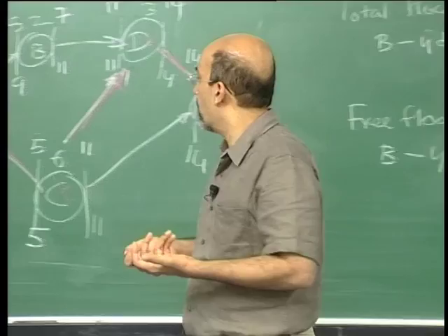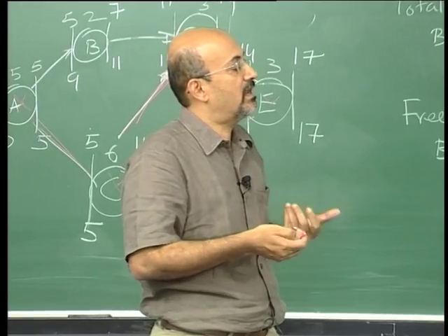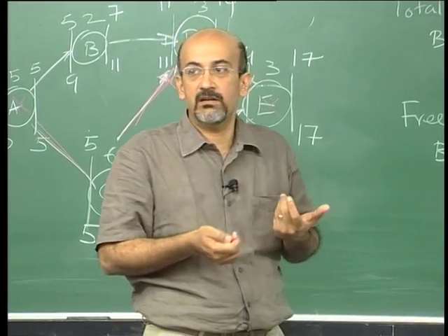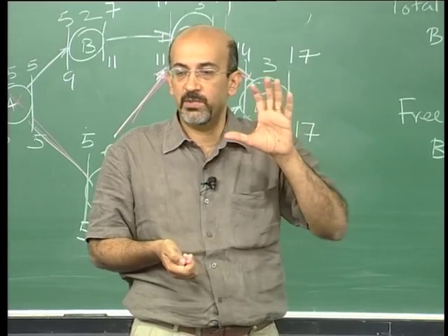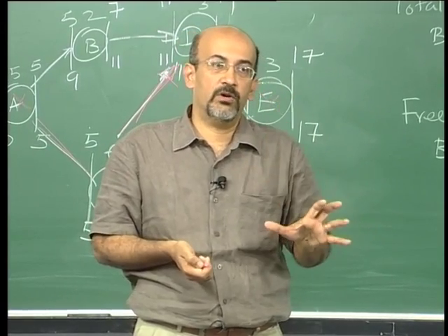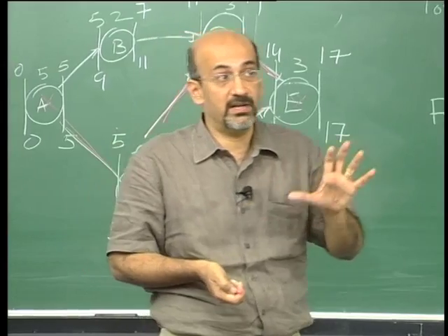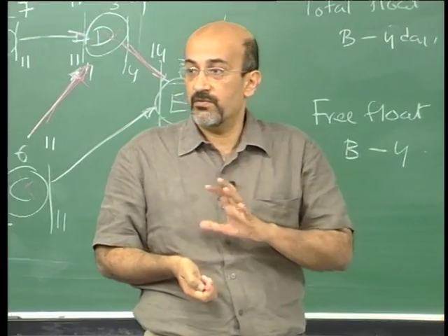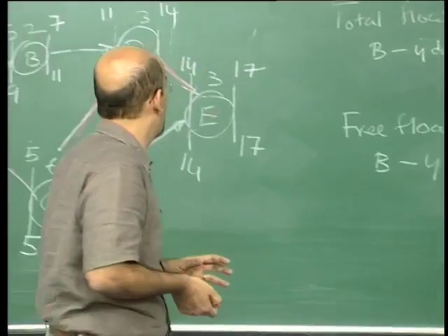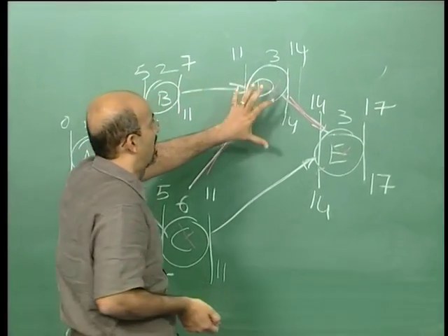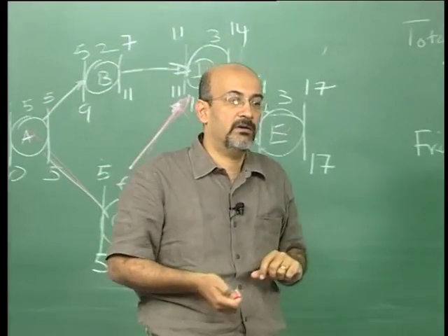So this issue of how float is shared is still an issue of a lot of litigation in places. And today when you take a contract document in an international contract, there will be specific clauses on who the float belongs to, and it always belongs to the owner today, and how the float should be apportioned in case of some need for requiring the float. So the subcontractors or the people doing each of these activities cannot assume that they have the float for themselves. So management of float has become a very key issue.